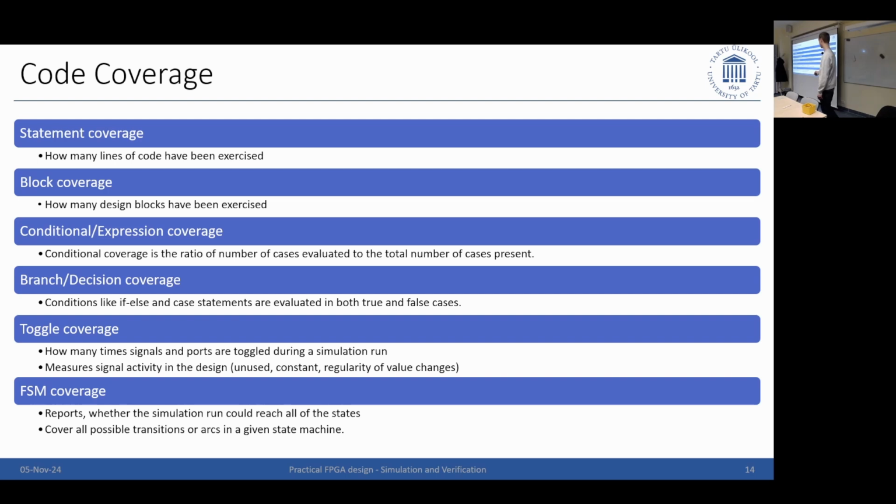So this gives already more information, and then you have a toggle coverage, which basically is less of a code coverage itself. It shows the activity of your signal. So do I have in my design states which are never activated or deactivated or only very few times? And this will give me a very good insight into how good my code is, how much activity some code areas have, and this might enable me to ask, why is this not even activated? It should be, or, I wrote this at some point for some scenarios, but I never use it, so you can throw it out of your code, and then you use less resources, right? Which makes my timing and my performance maybe better.